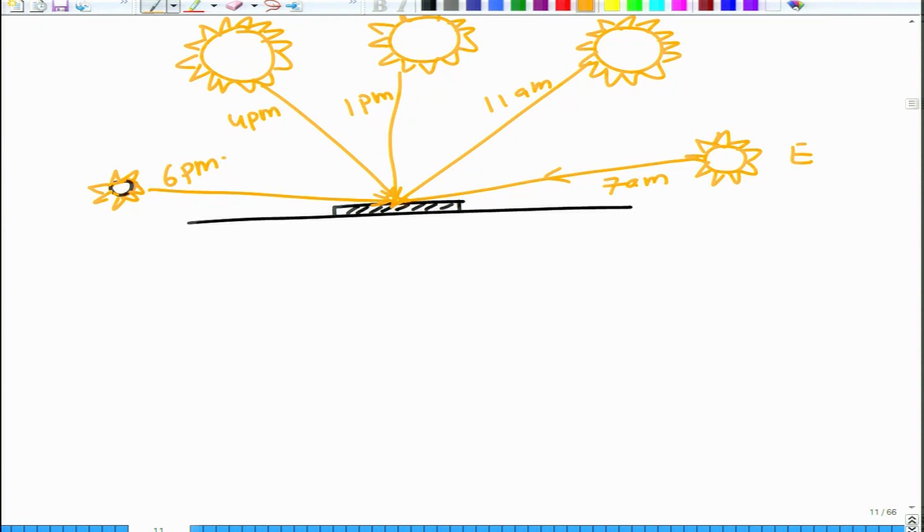So, this is how the sun is going to travel, which means the distance the light has travelled to reach that particular point has changed, and you need to normalize it, because you can do one thing, that your solar panel can remain vertical, or your solar panel can remain at an angle which gives you maximum absorption with respect to the sun position all the time, which means as the sun moves, you will have to make the solar panel move also. Okay, that is one possibility. If you can't do that, then you will have to position your solar panel in such a fashion that you average out the rotation of the sun, so that the average intensity received on the surface of the solar panel is maximum.